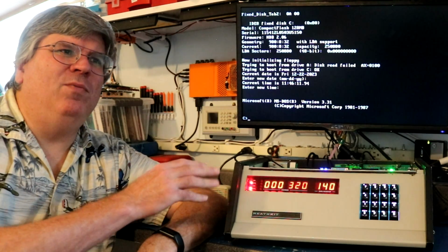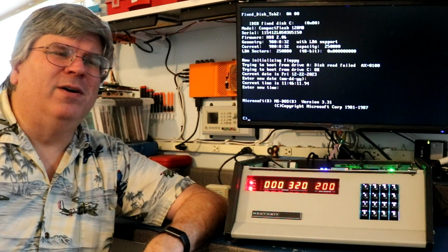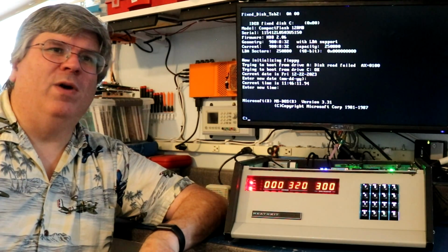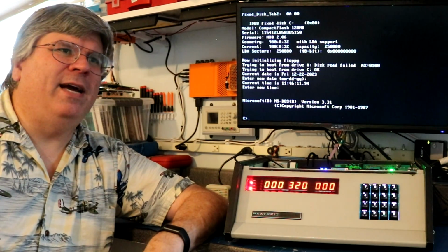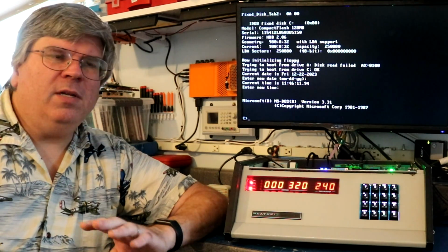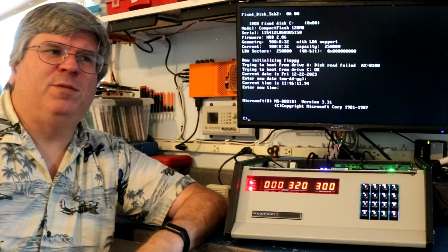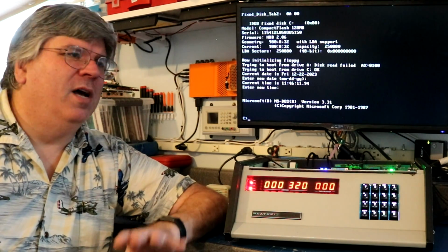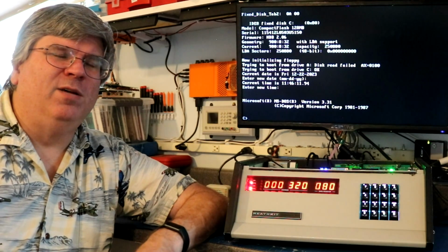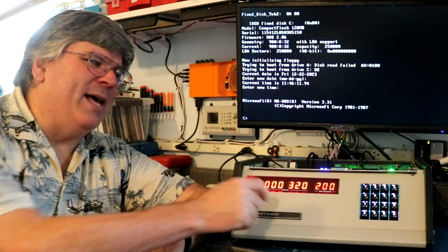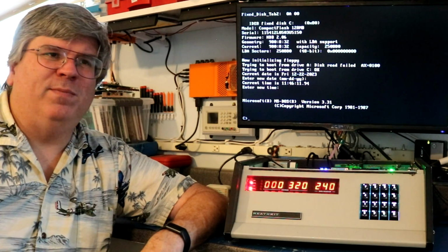So how do you do that with an 8-bit Heathkit computer? Well, I put all of the RAM on the CPU board as well as the ROMs on the CPU board, and then I use the Heathkit's bus strictly as an 8-bit I/O bus. So I intentionally started this project not with the intent of making just a single board computer, although it does function as that, but making a single board computer that could use these H8 peripherals, including the front panel display, which you see is currently running its front panel monitor.